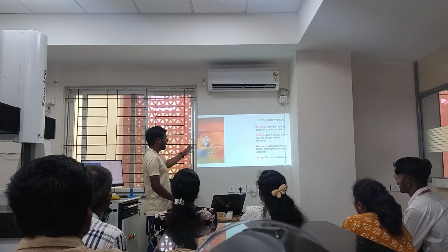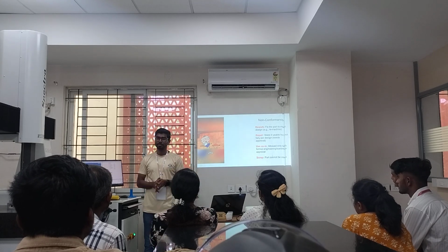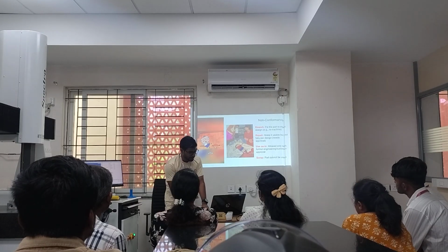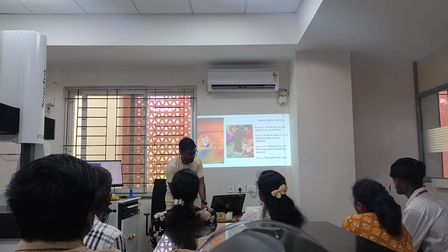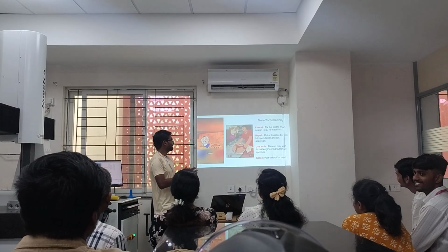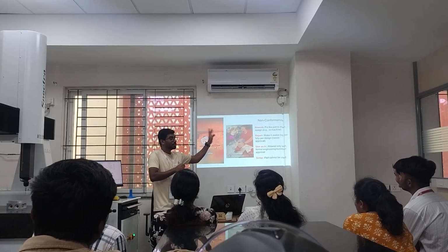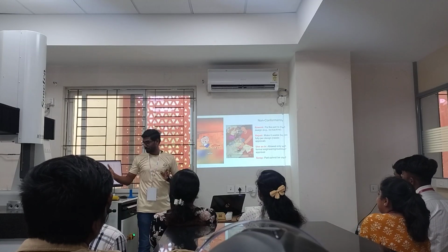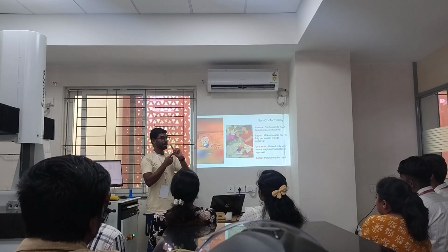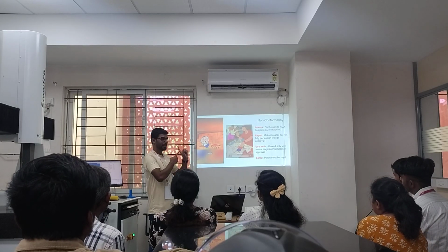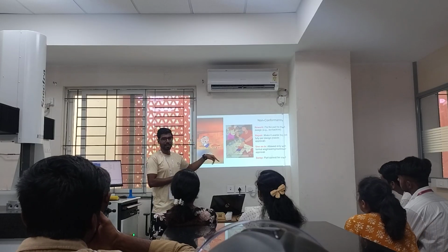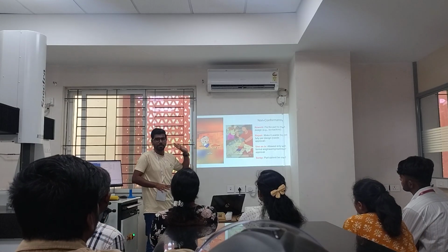Okay, so the thing is that he is a naughty guy. Similarly, our parts can be naughty. They might go off dimensions. What will happen then? There will be results, and this part will get beatings. If there is a non-conformance of our part, what is going to happen? We have four options. We can do rework, we can repair it, we can use it as it is but only on the approval of the design, or else we can scrap it. So these are the four options we have.